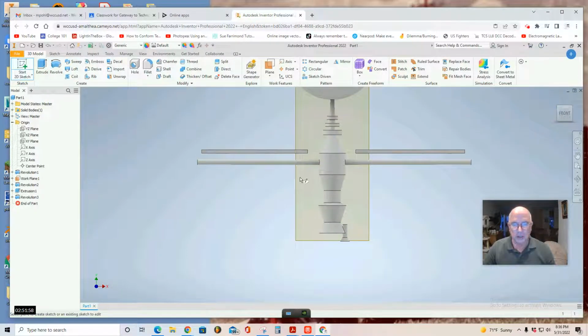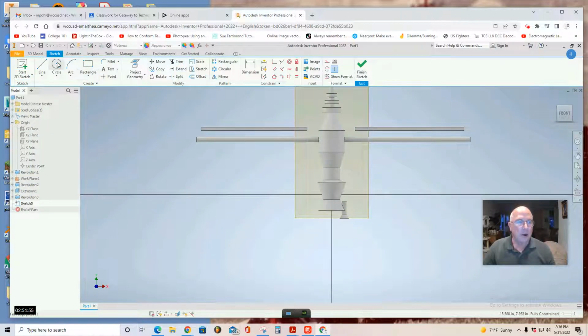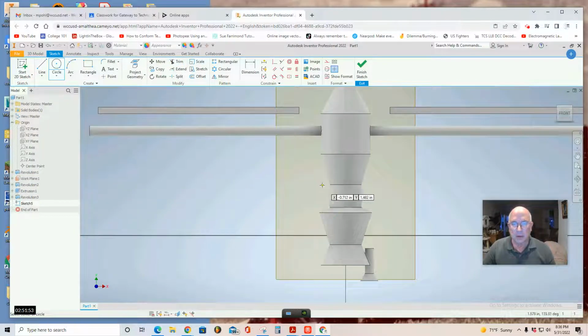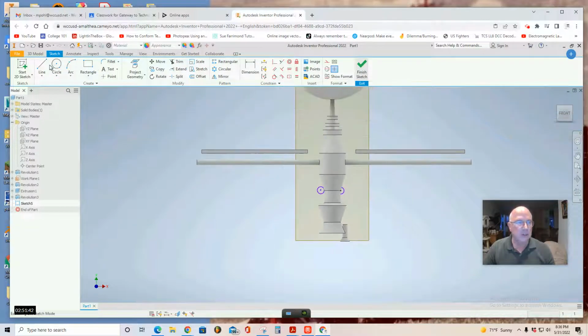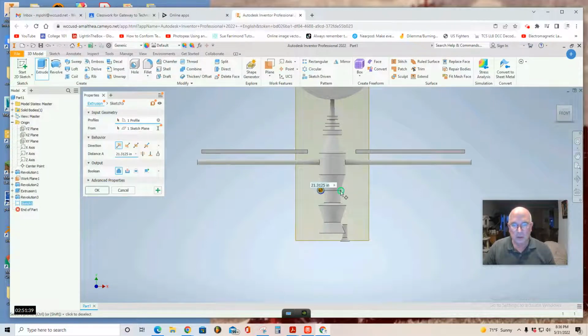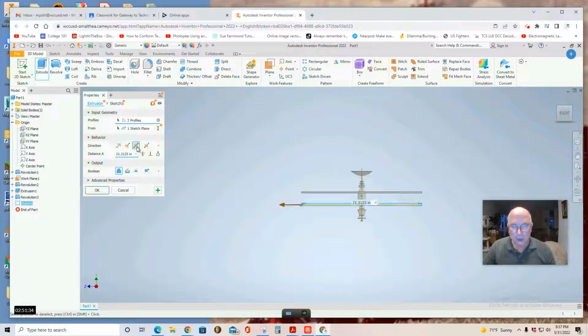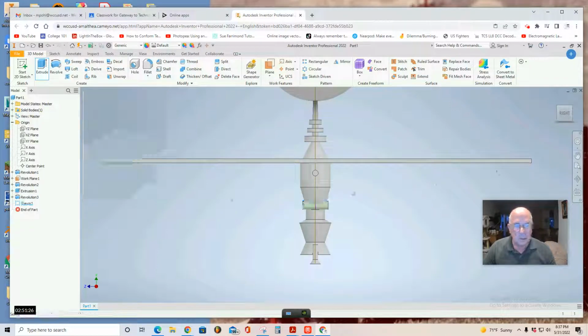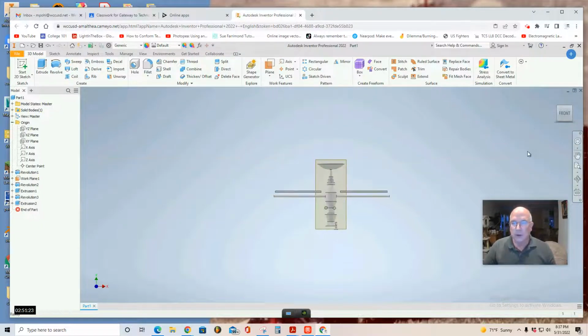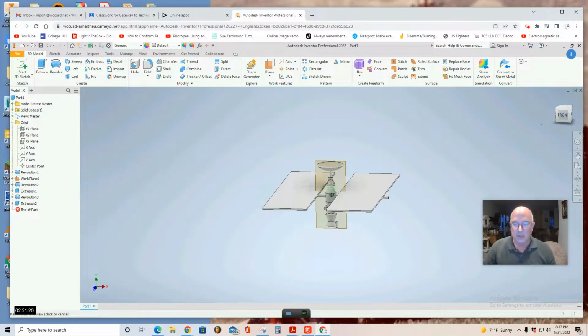And start a 2D sketch, click on this XY plane. I can also, let's say, put a cylinder here. 1, 2, finish sketch, extrude both of these items. And turn them a little bit so you can see what you're doing. You want to go left and right and just grab this arrow, bring it in. Click OK. I have no idea what these are. It's just an imaginary concept illustration.